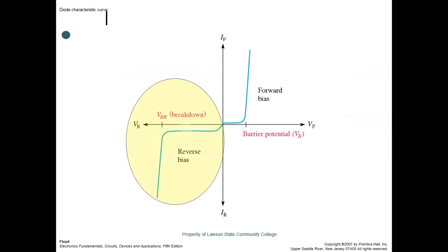So this is the breakover region right here. As long as we keep it below that breakover voltage, this is going to act like an open switch. Is there going to be current flow through it? Yes, there is a path. You have a difference in potential. And what do we call that current that flows through it in the reverse direction? Leakage current, yeah.